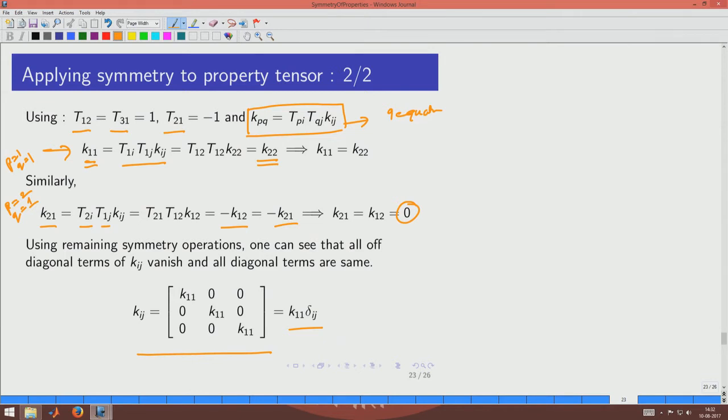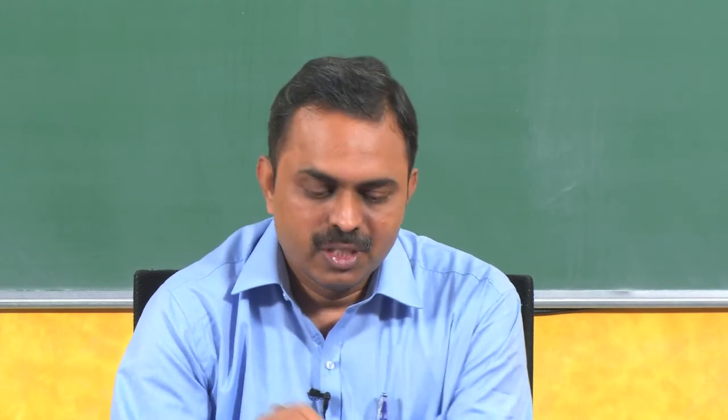So, the 4-fold symmetry is as good as infinite symmetry. But that is only because it is for a second order tensor. For a higher order tensor, it is not guaranteed. So, this is how the symmetry principle is coming of use. Neumann principle is helping us know that a second order tensor of symmetric nature can be reduced to just an isotropic tensor. Now, why is isotropic useful? Because later on we will have fewer numbers to handle.